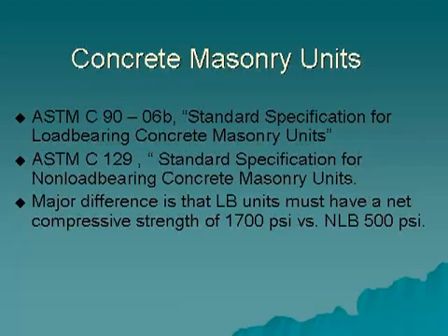So obviously it's going to require a great deal of care to be able to tell these individual units apart. The point here is you certainly wouldn't want to install non-load-bearing concrete masonry units into a wall that is intended to be load-bearing.